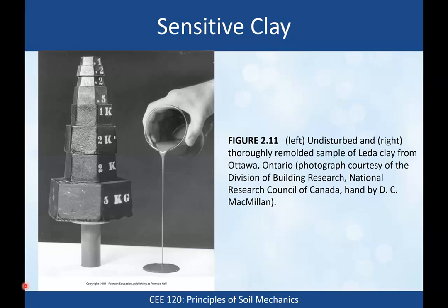But what happens is that marine sediments are often subsequently lifted up out of the ocean, like at the end of the Ice Age or something like that, and the sodium cations then come in contact with fresh water, and osmotic pressure pulls them out. So the sodium cations get leached out of the clay, and then they're still stable in that configuration, but as soon as you start disturbing them and that positive end of the clay mineral clicks off of the negative end, now they're pushing each other apart really hard, and it becomes like a liquid. So it's an interesting aspect of soil behavior.